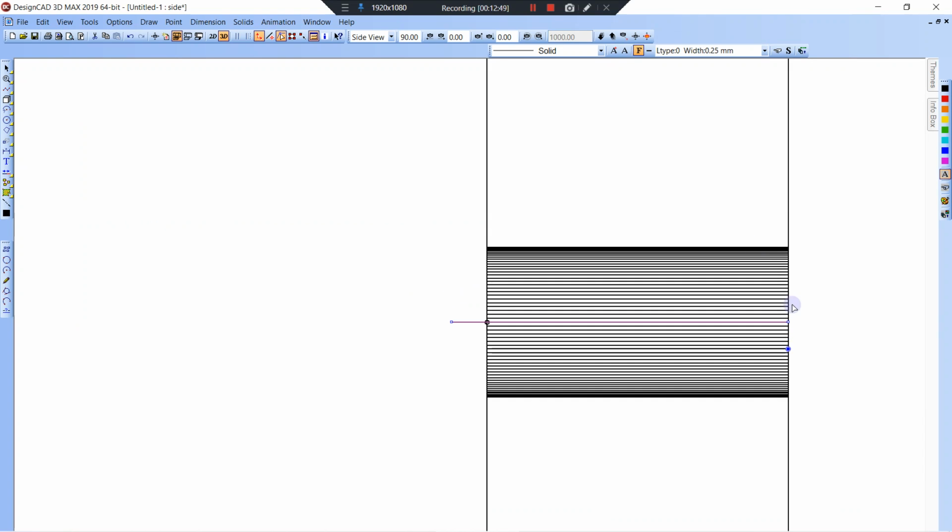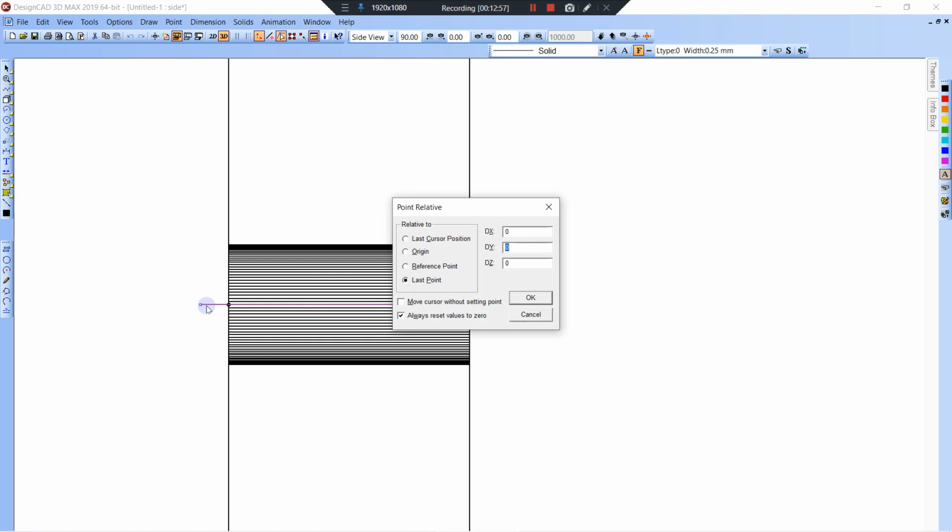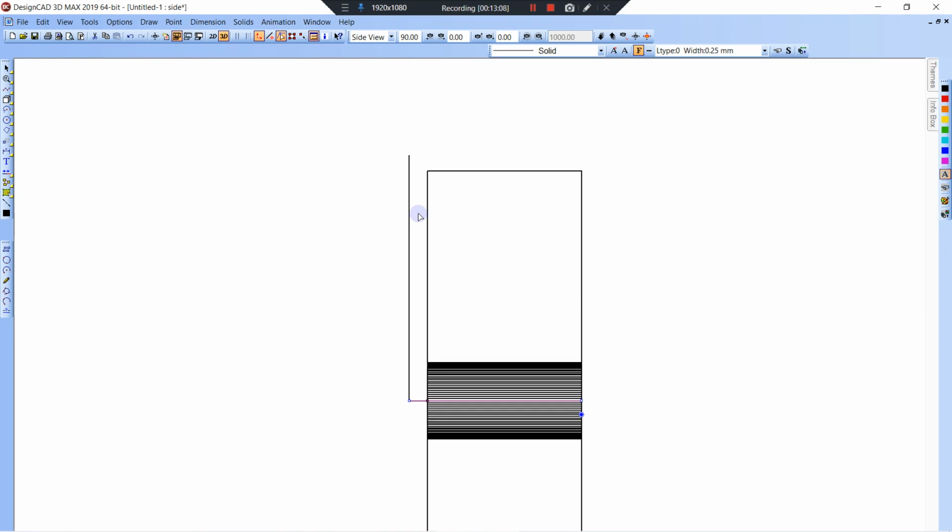So now we're going to look at this V point relative 0.25 vertical, 0.25, I think that's too big, 0.2, enter. I'm just looking at something that will work for this angle. So I'm going to leave about 1/16 of an inch shoulder here. So it's going to go from here, V, to there. And I'm going to 3D that so I can get that frustrum to develop on top of there.